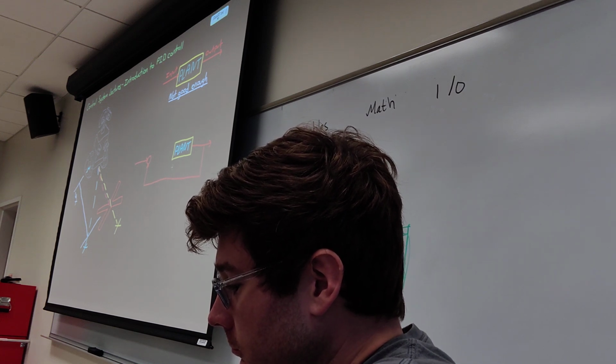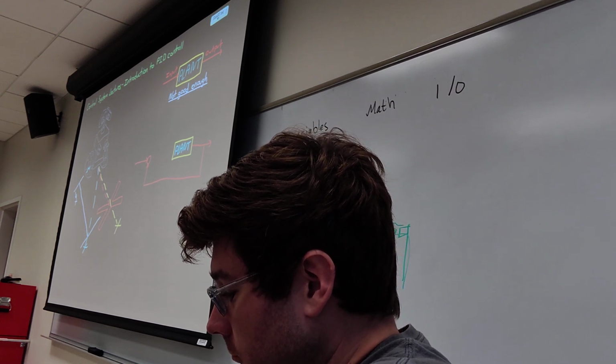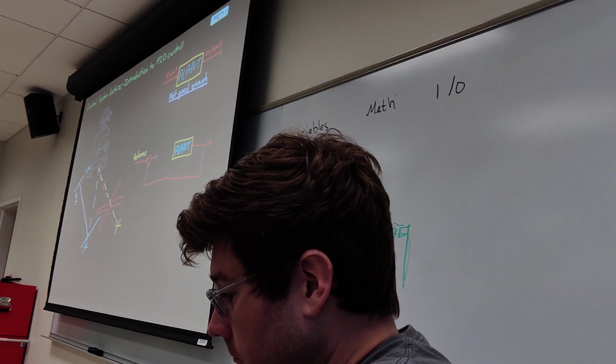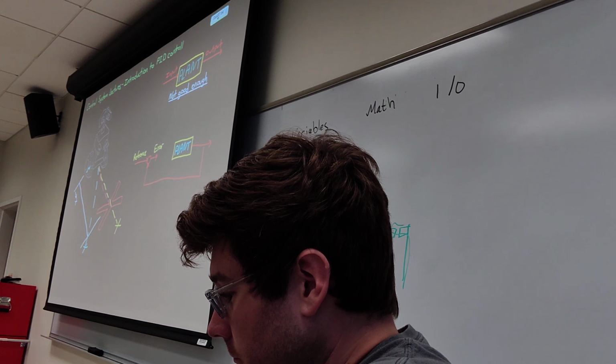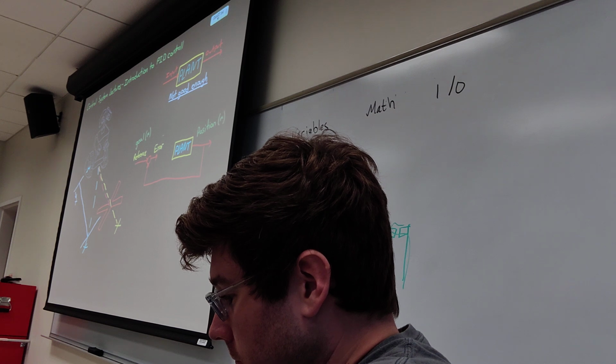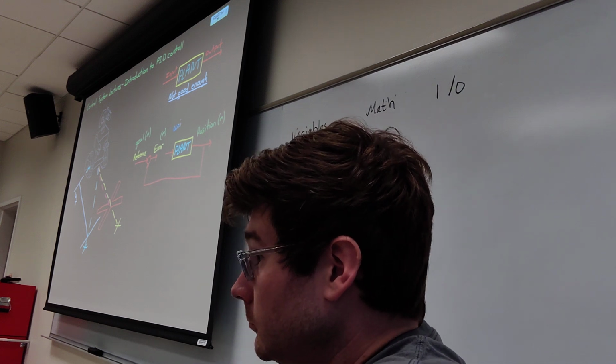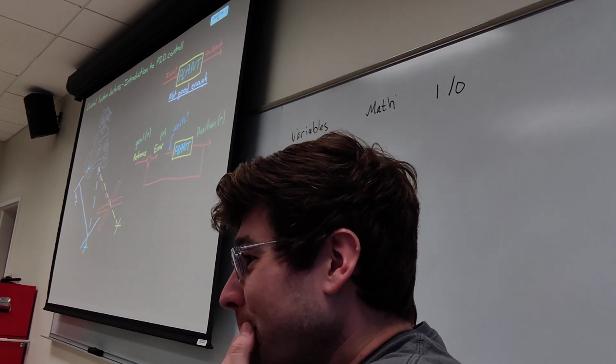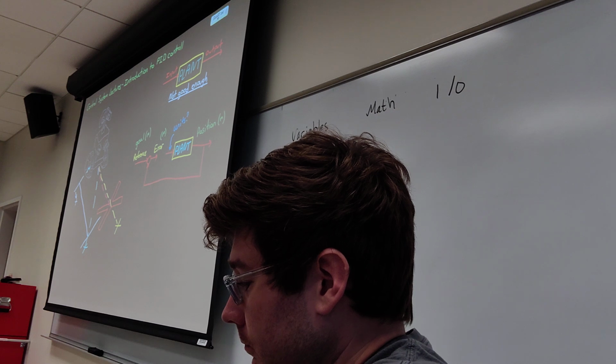Now in a feedback system, there's a reference signal, and this is the desired value or the ultimate goal. And you compare that to the measured value, and what you're left with is the error or the delta between where you are and where you want to be. So in the case of the robot, the error would be the difference from the reference position, which is the distance from the start to the red X in meters, and the robot current position, which is measured by the robot, also in meters. So at this point, we need to figure out how to convert an error signal that has units the same as the output of the plant into an input signal that has units that may or may not be the same as the output.